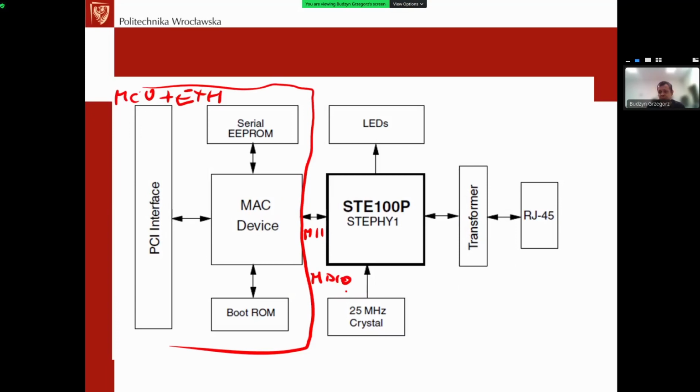Simple from the USB port side, and or from the microcontroller, depending on what you need, but you can choose them. The configuration method works as a fuse. It's that simple. So you can use UART, you can use SPI, you can use I2C, you can use a parallel interface. So plenty of options we have with the interface chips. That's in case of USB.